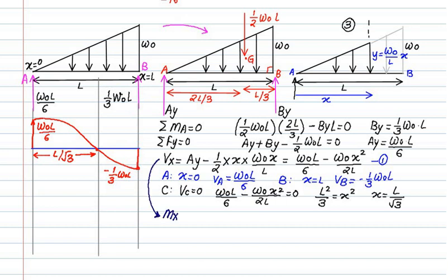Start collecting the moment equation, and we will write down the moment equation from the Vx equation. So if you multiply Vx by x, you will get your moment equation. If you refer to figure number 3, what is the moment of RA, that is AY? This moment is a clockwise moment, and the distance of this AY from point A is x, so that is a positive quantity.